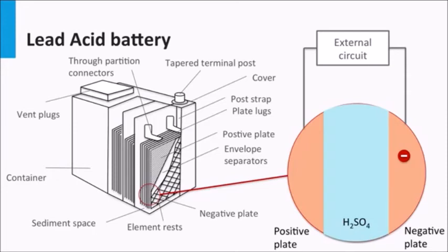The active mass in the negative electrode is lead, and in the positive electrode is lead oxide. When electricity is drawn, electrons flow from the negative to the positive electrode through the external circuit, causing a chemical reaction between the plates and the electrolyte. This forward reaction also depletes the electrolyte, affecting its state of charge, or SOC.